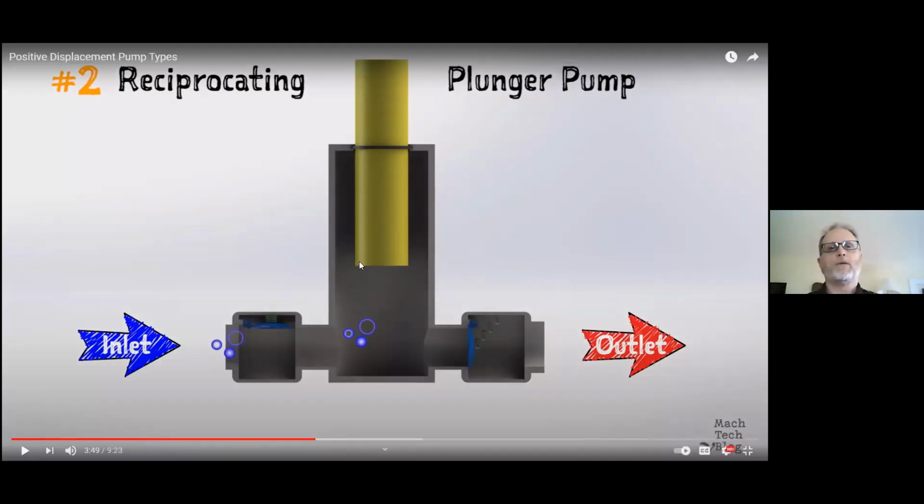And when we were doing hydraulics, I showed you the Africa Dev pump that's used in many places with no power, and it's basically the principle of a plunger pump. The handle is pulled up, and the plunger is dropped and then pulled back, and it helps displace the water in the column and brings out a fixed amount, basically the same amount of water as the area and volume of the plunger itself, and that fills the buckets or containers at the surface.